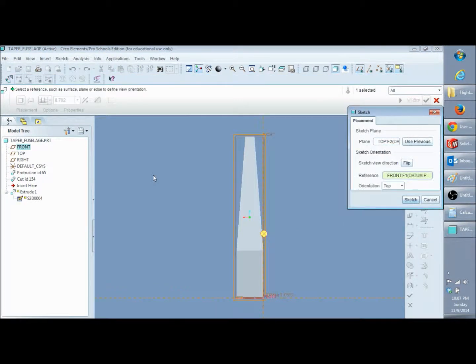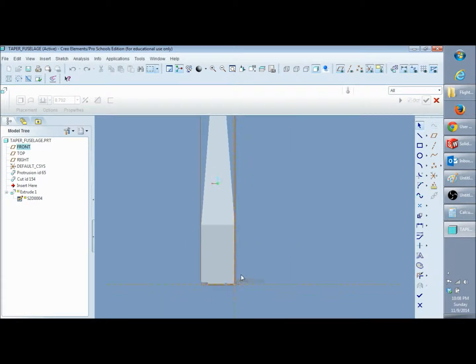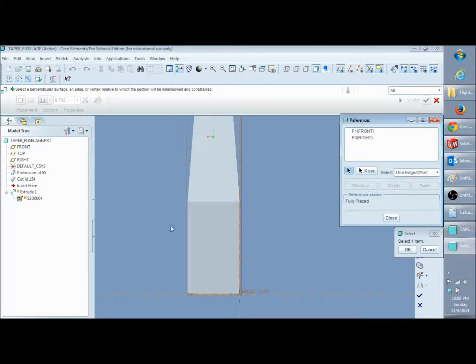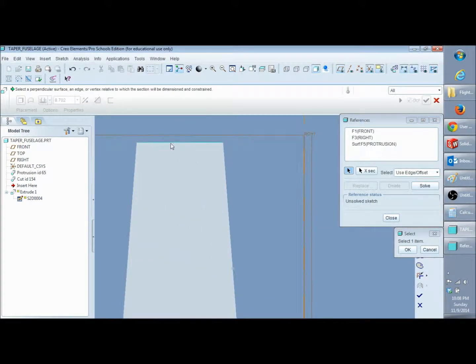Hold right click, and then that menu will pop up, and just hit that sketch internal features, or sketch, whatever. So this is all good. The sketch plane is top, which is what I want. It'll automatically select a reference plane, so it's all good. What I want to do is go in and add some more references. Go to sketch, references, and select the edges that I want.